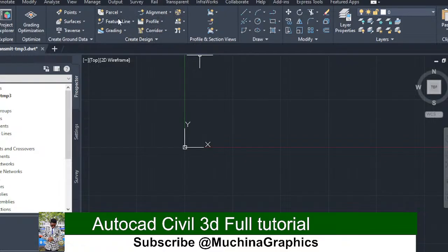All these things you get to understand. For the profile, we have the vertical profiles, and when you create the profile, you get to understand the steepness of your area. So you get to understand the gradient of that area, and with that in mind, you can calculate the volume of the area that will be cut and also the area that is going to be filled.